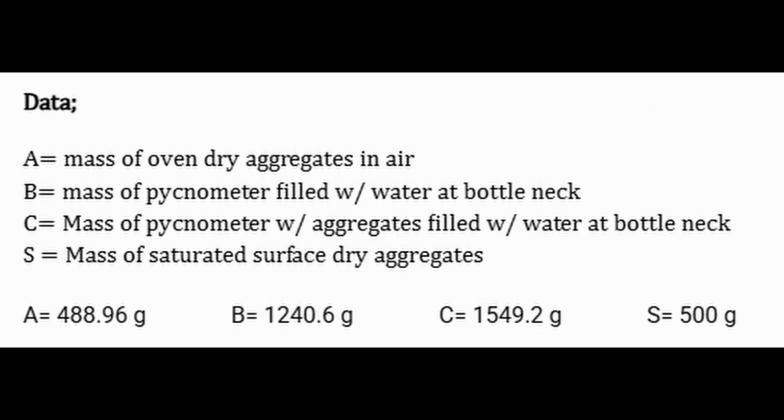Data. Here is the data that we have accumulated throughout the experiment. Letter A stands for mass of oven-dry aggregates in air. Letter B, mass of pycnometer filled with water at bottleneck. Letter C, mass of pycnometer with aggregates filled with water at bottleneck. Letter S, mass of saturated surface dry aggregates. For letter A, we got 488.96 grams as the value.